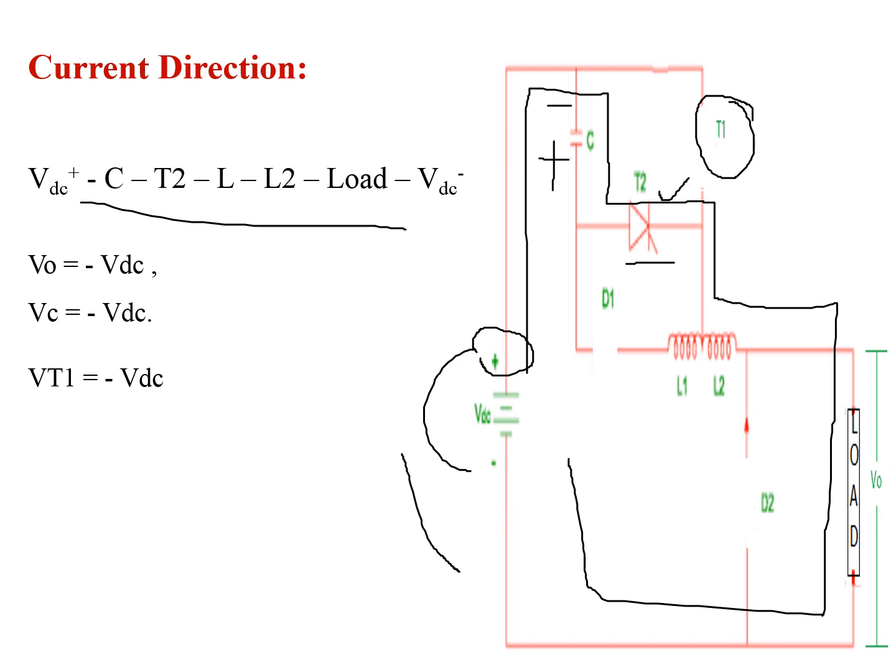In this case, the total input voltage appears across the capacitor but as a negative. Why? Because the polarities of the capacitor are negative and positive. So the total amount of input voltage appears across the capacitor but as a negative. Here thyristor T1 acts as an open circuit, which means the total amount of voltage across the capacitor appears across thyristor T1.